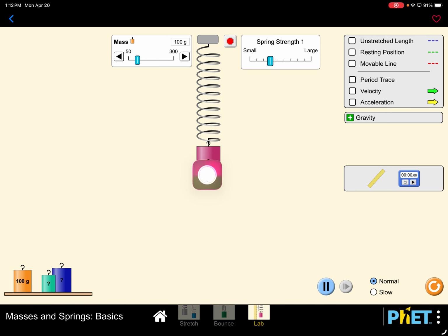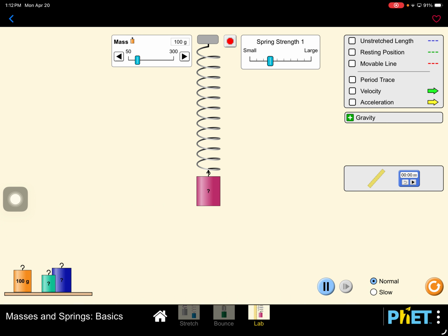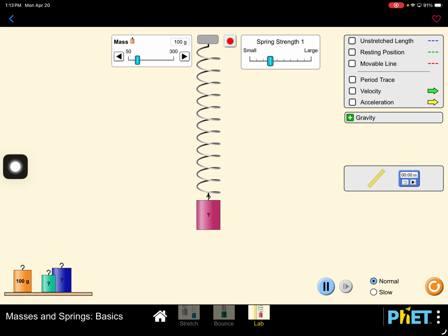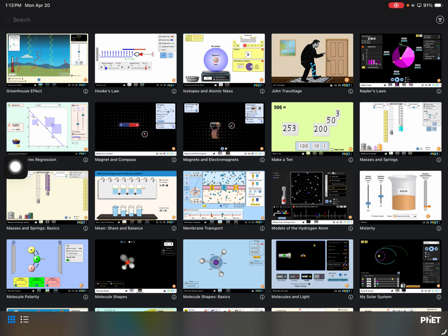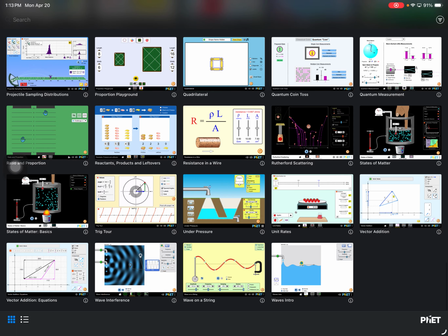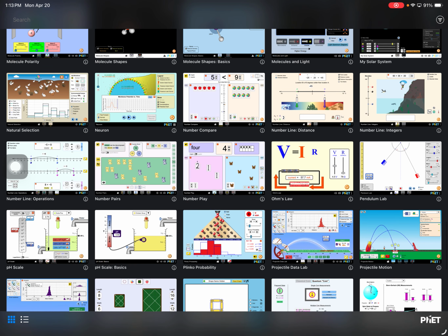So it has potential energy and kinetic energy, and the system will oscillate when the energy goes back and forth from one form to another. And of course, when energy is conserved, you don't want mechanical energy to be dissipated. So for a system to oscillate, you need at least two different forms of energy, and where energy is not dissipated.